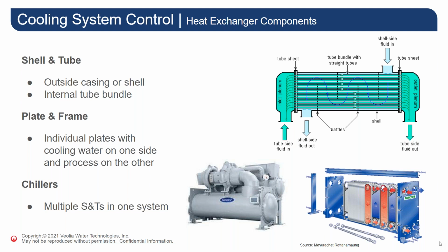A similar problem occurs when dirt or debris or microbiological growth plates out on the heat exchange surfaces. Lastly, any of the deposits or fouling could lead to under-deposit corrosion, as Ted mentioned, of the actual metal heat exchange surfaces themselves, which leads to a future failure of the heat exchanger.